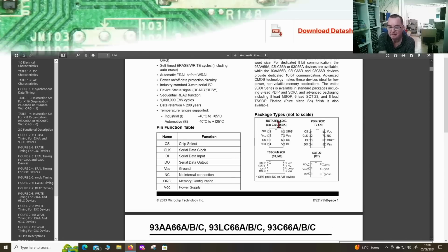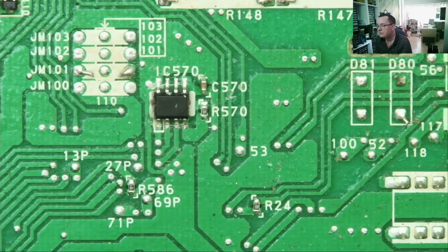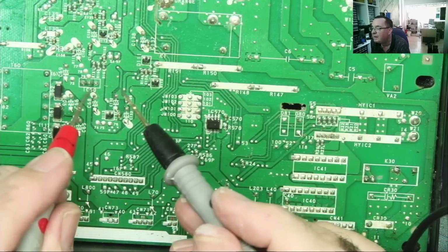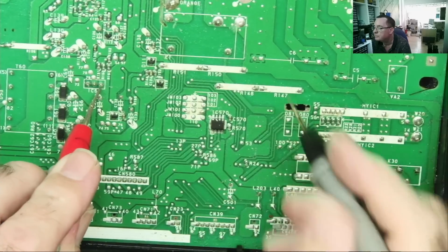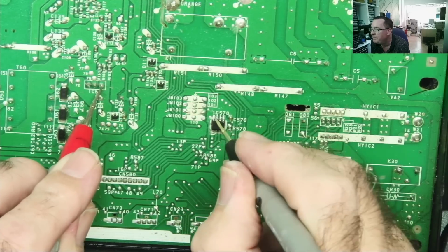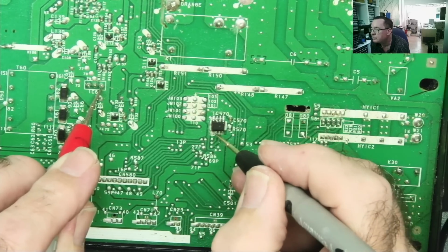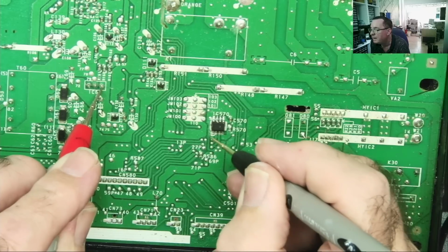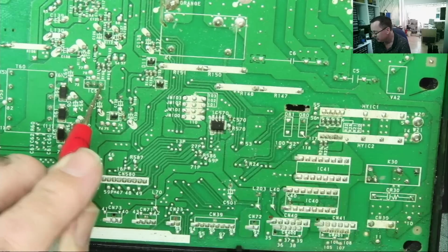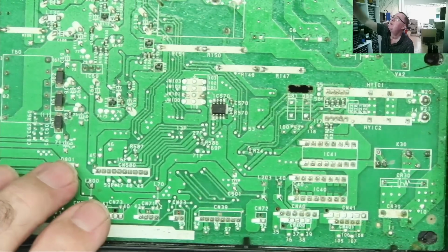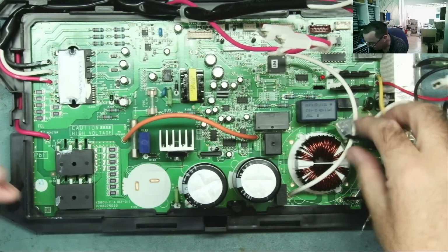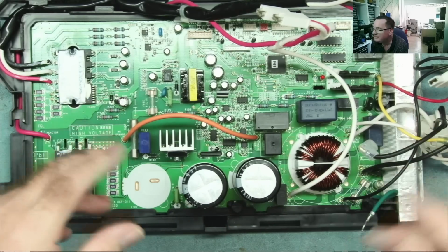Right, we need a plan. Well, we can solve the mystery of the pinout easily enough. So here is our voltage regulator. This is the output, the 5 volts. So that goes to, yeah, pin 8, which is there, not pin 2, okay? So that is the power, and this would be the chip select on here, okay? So at least we know the pinout. So I suggest we power this up. We know where the power comes in, so that's not too difficult to do.